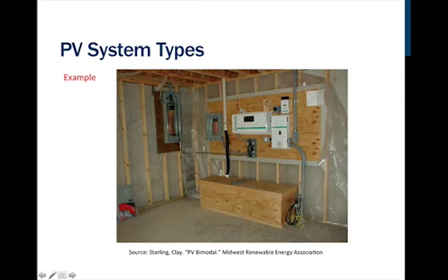We come out of the battery pack to the inverter, out of the inverter over to the main house panel, and when the grid goes down, the inverter will disconnect from the house panel and power up this critical load panel, which is going to power up refrigeration, well pump, heating, whatever we need to run during a power outage. When the grid comes back up again, the inverter senses that, relinks with the grid, and we're up and running. We don't even know that happened.